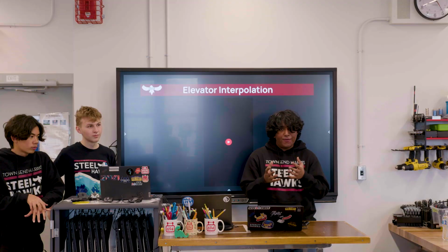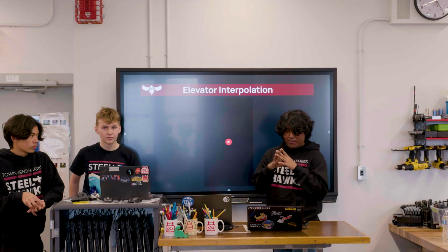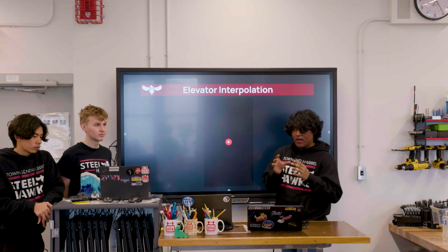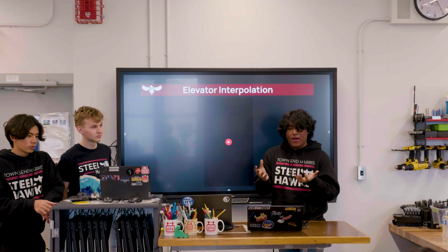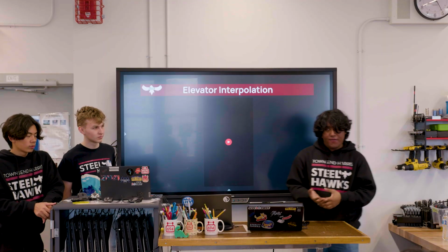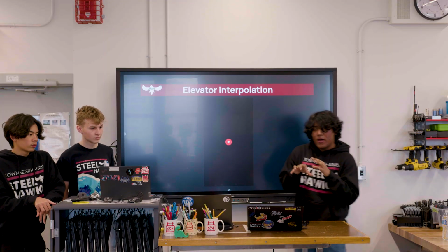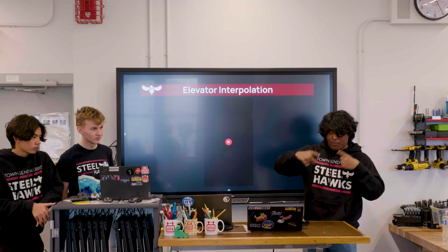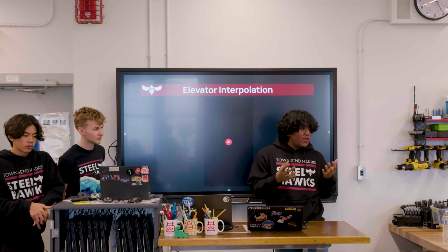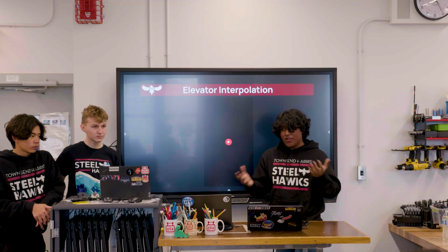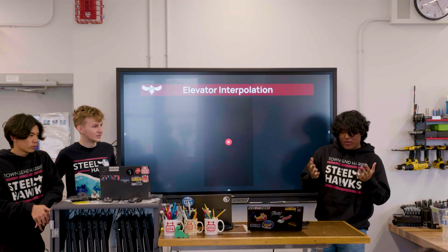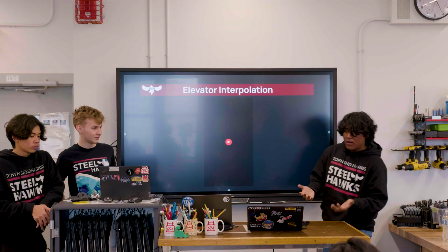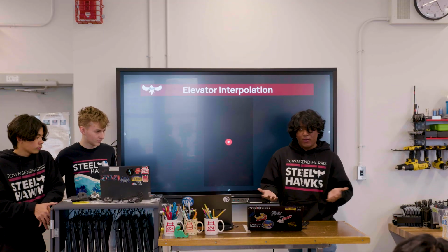You're able to detect if something's in the way if you're drawing a lot of current. In our auto line, the way we check is our initial pose will try to be flush to the reef, because that's your best case scenario, right? If you detect that your drivetrain is drawing a lot of current, that usually means there's something obstructing the way, so your motors are drawing more current to run at that velocity. As soon as you see your current is drawing more than it should, you have a good understanding that there's something in the way. So we use current sensing to see if there's something in the way, and depending on that, we'll change our auto line setpoint.